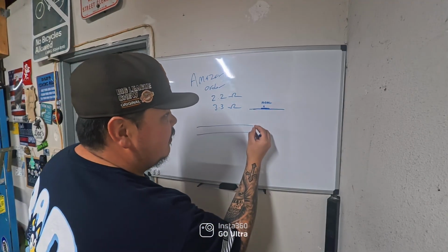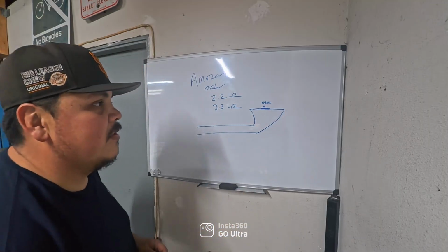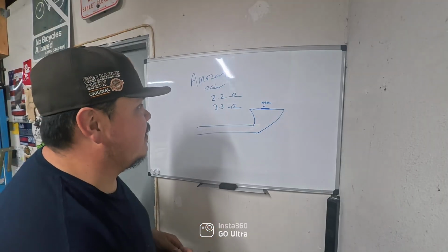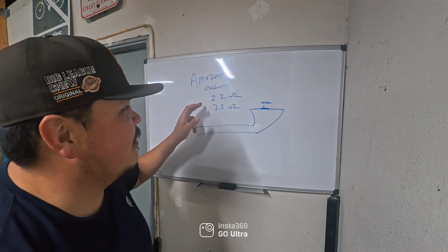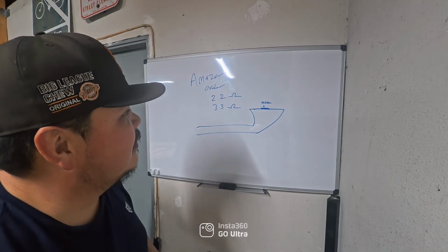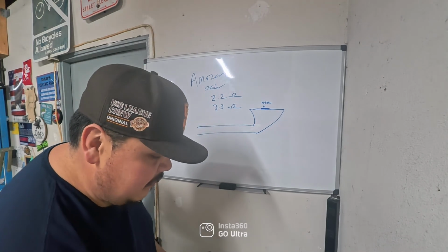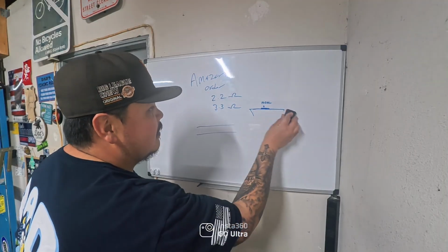So all you're gonna do is put the resistor in line with the 2 wires, clear the codes, rescan it, and see if the codes are still there. So you can order them on Amazon. I believe if you could find something at least close, like a 2 ohm and a 3 ohm, I think that would be good too. So you can make your own dummy load resistors as well.